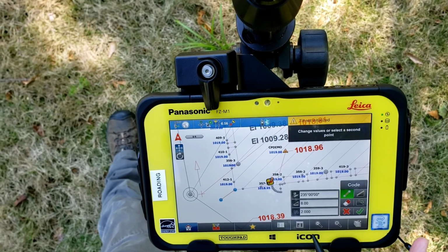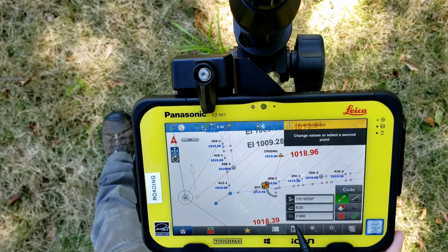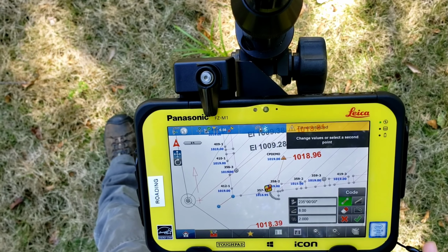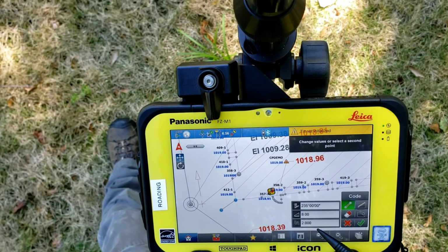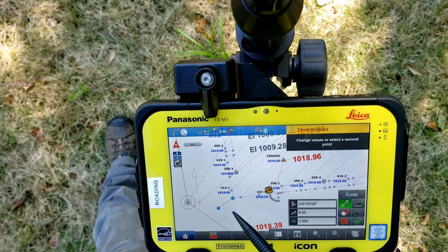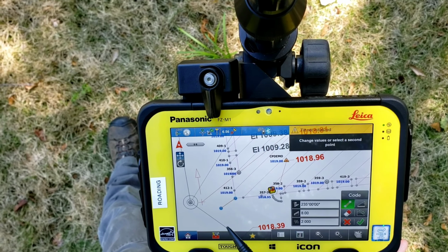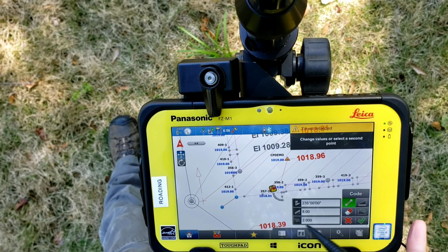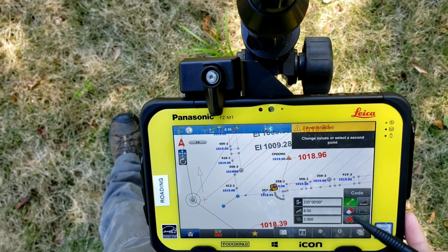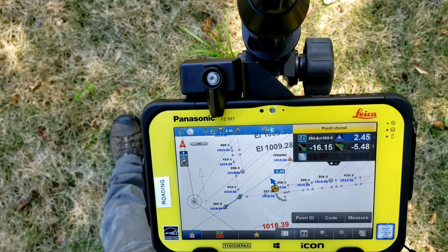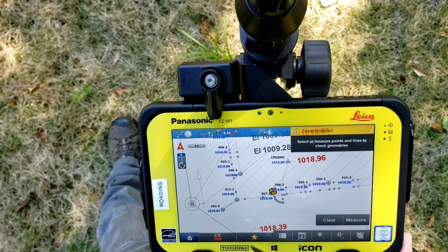So an important thing here, this is going to be 8 foot horizontally, linear feet. It's not going to be slope distance. So when you hit this green check, the distance between those 2 points horizontally is going to be 8 feet. If you want to run this line out 8 foot on slope distance, it'll still be a 2% line, but your line is going to be 8 foot slope distance. So pretty handy tool though, definitely. So just to give you a quick show of that, checks.